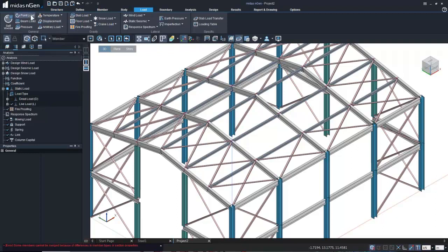We can apply point loads, beam loads, and there are arbitrary loads. Arbitrary loads are for when you do not have an actual element at that location, or let's say a partial loading on a particular element is required. That can be performed by creating firstly a line body and then applying the arbitrary load on it. There are various functions. There is arbitrary point load, arbitrary line load, pressure load, and so on. We will be seeing all these different types of loadings in our further training sessions that are going to take place.